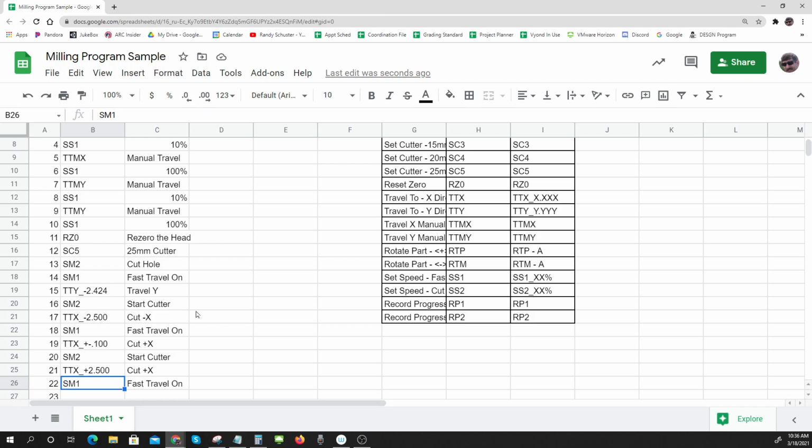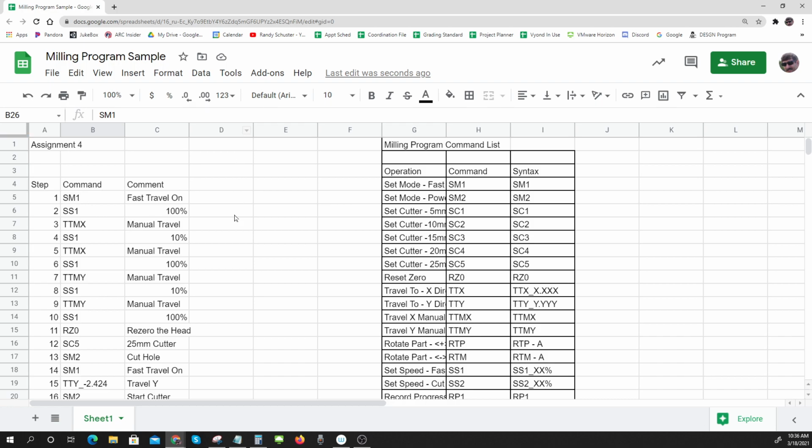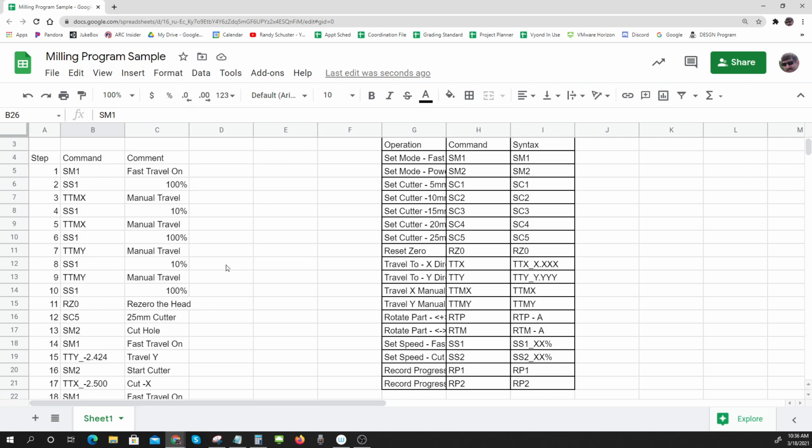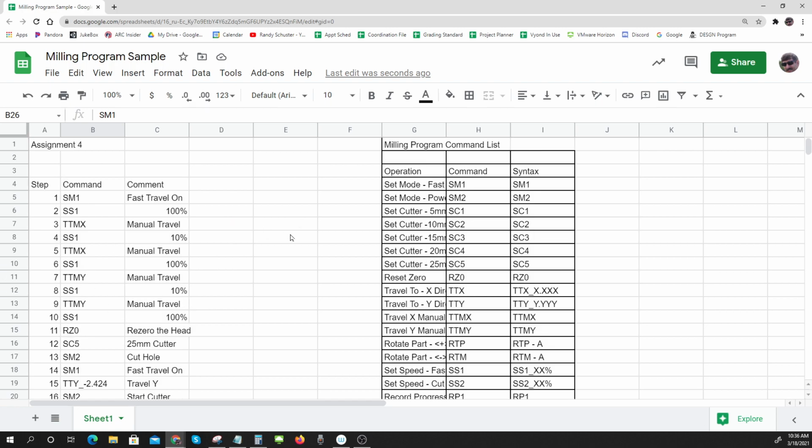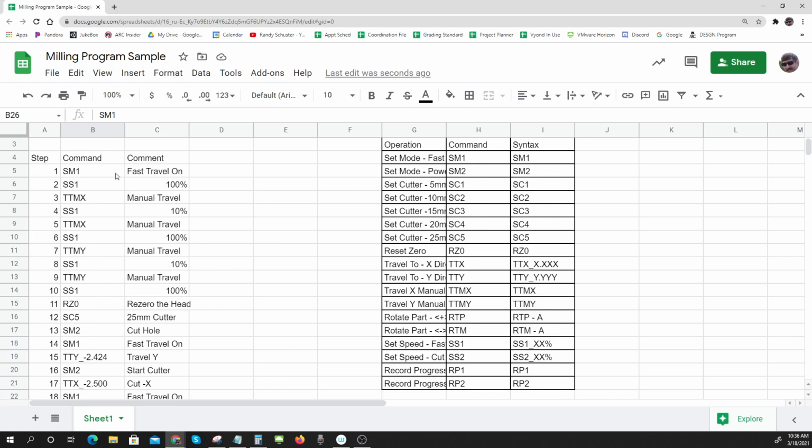Cool. So every time what I do, and this, believe it or not, machinists do this. There's a mode on most machine tools called dry run. And it does the program, and you just don't have the block of material there. And so you push dry run, and it does exactly what your program does, and it lets you imagine all of these things. Well, we don't have one called dry run.